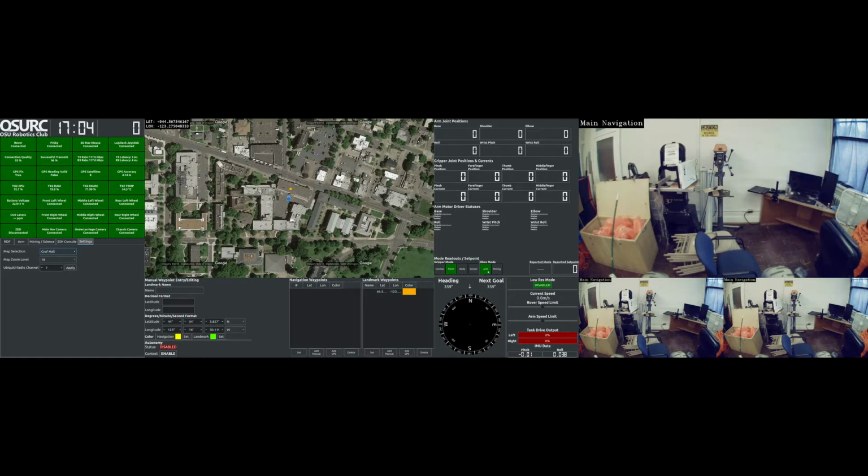These give you full readouts for the states of every motor controller inside the ARM, whether there are any faults, and then gives you an idea of what you need to do to clear them. It also tells you things like whether or not the motor drivers are actively moving an axis. Really just a lot of useful information to have at a quick glance, just to do a sanity check, make sure things are working right. Again, you can use that clear faults button to clear them when they have errors.